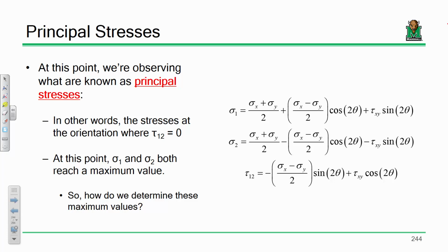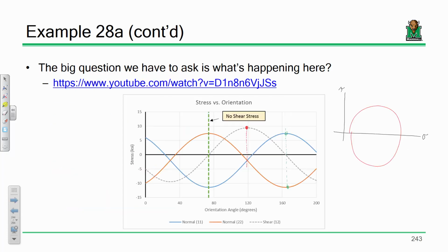So what we're going to do next time is take this state of stress and try to define two things. Number one, what is the maximum shear stress overall. The second thing we're going to define is what are called principal stresses. Principal stresses are these stresses here and here. We're talking about that stress and that stress. What is the absolute maximum normal stress? Because as a designer, that's what you care about. That's what you need for the purposes of design, and we call those principal stresses.